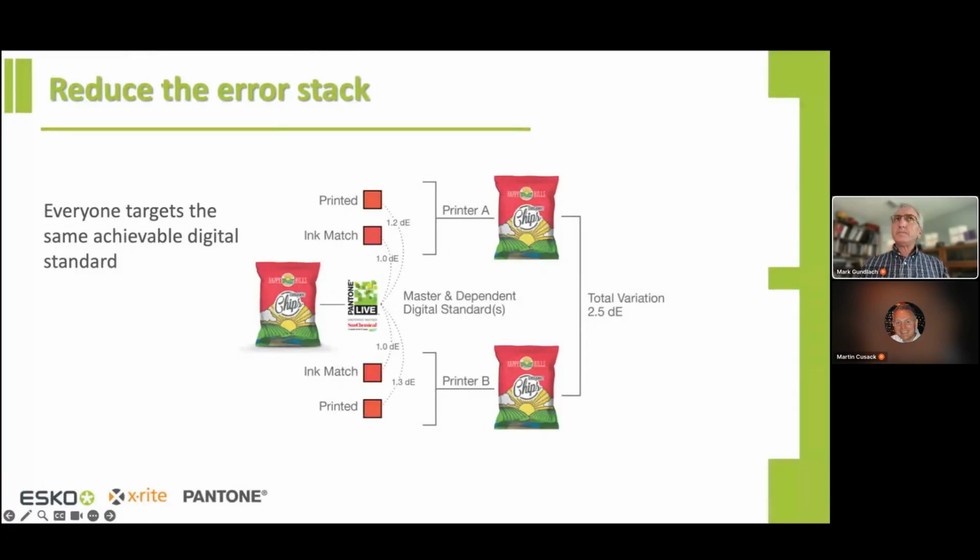So when you're using software like ColorCert or IQC or any number of other QC applications, there are options to export out a CXF. And oftentimes they'll offer you options of what to put into that data. So you could put in just LAB, or you could choose to add the spectral data. If you're creating a new standard you want to share with others, especially the ink formulation people, make sure that you add in the spectral data in that CXF file.